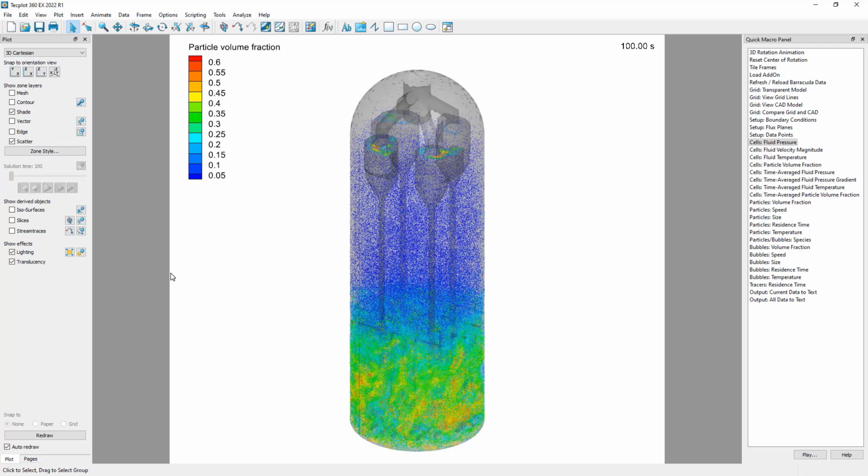So our simple way of doing this without doubling the memory or increasing the memory load in Tecplot is to select the frame and then do Control-C. So we're just effectively copying our frame. And then we'll do Control-V to paste our frame. And I'm going to do that twice. 1, 2. So now there are 3 frames here in this Tecplot window. We can only see one because they are stacked on top of each other.